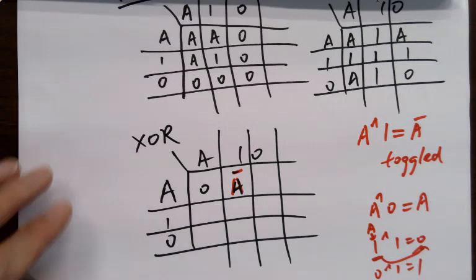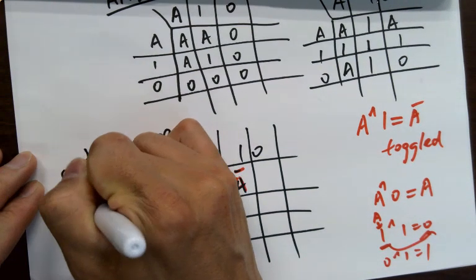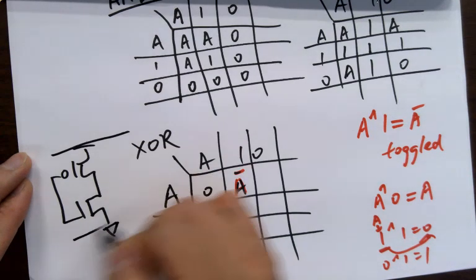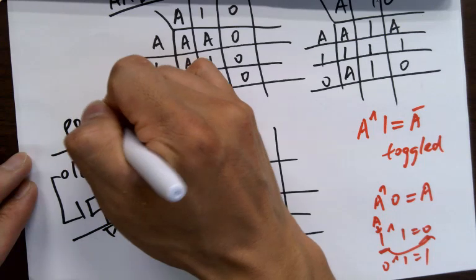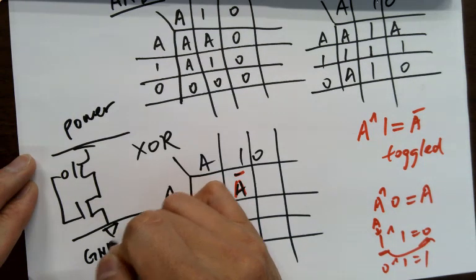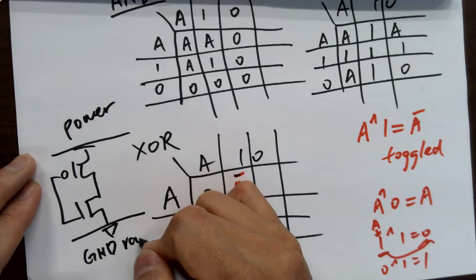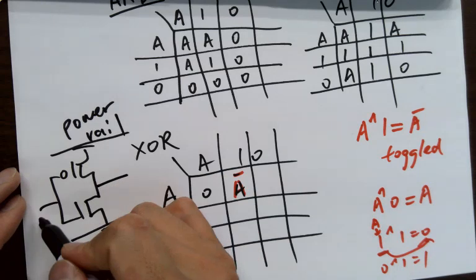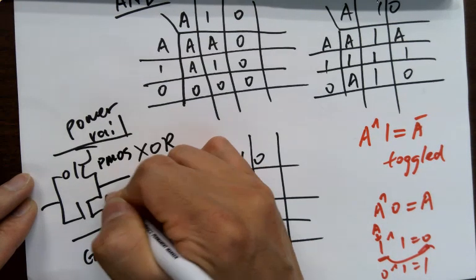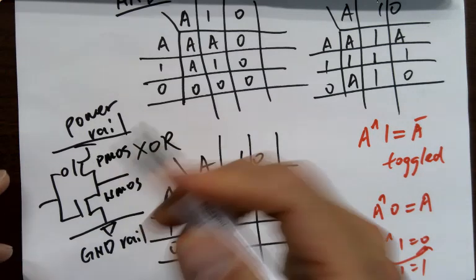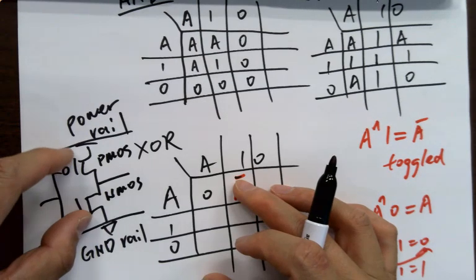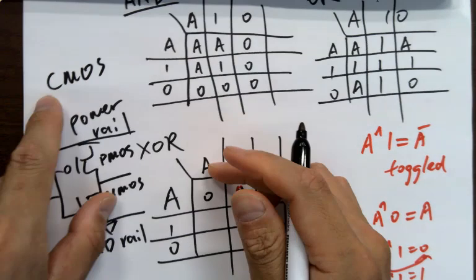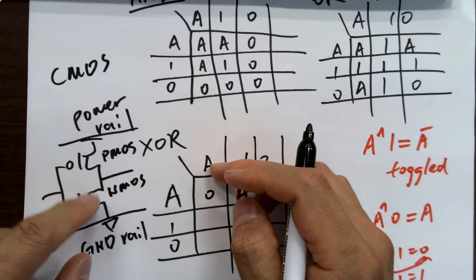Why is that? Because in integrated circuits, all the digital logic is formed by gates, and these are just two rails: a power rail and a ground rail. Whenever you have the output, for example, this is the input, this is the PMOS, this is the NMOS. It's okay if you haven't learned that yet. Just know there are two transistors, complementary MOSFETs. That's why it's called CMOS, complementary metal oxide semiconductor. The PMOS is P-type and the NMOS is N-type.